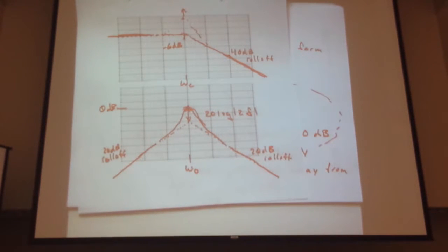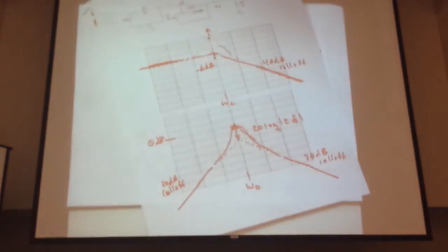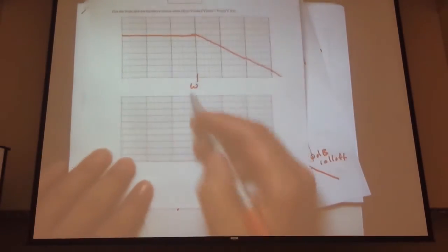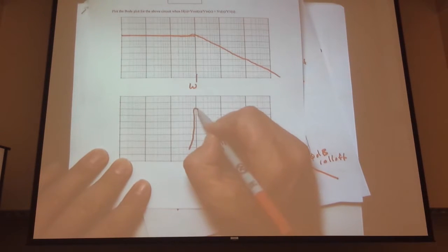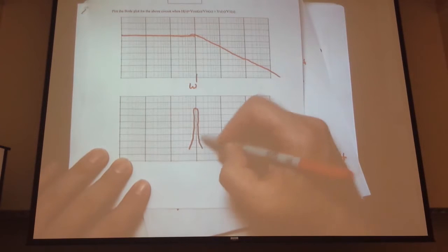And so that's just a way of locating where our inverted V starts. Our inverted V always has 20 dB roll off on either side, high frequency side or the low frequency side. As you underdamp this more and more, this becomes narrower and narrower, at least relative to our response.